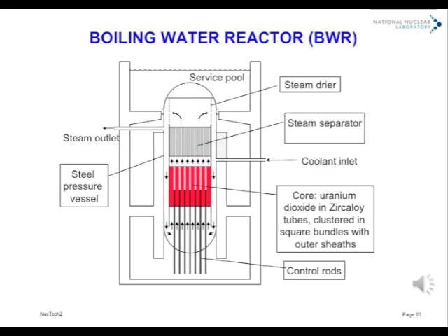The boiling water reactor, BWR, is rather similar, except that the primary coolant is allowed to boil and to drive the turbines directly. It thus saves the cost of the heat exchangers, which tend to have trouble with the welds of the tubes, but complicates maintenance of the somewhat contaminated turbines and condensers. Because of the steam separator above the reactor to remove drops of water, control rods are inserted from below.